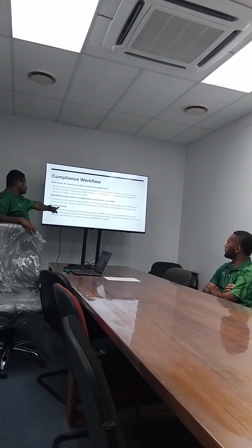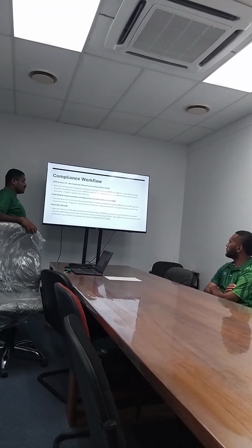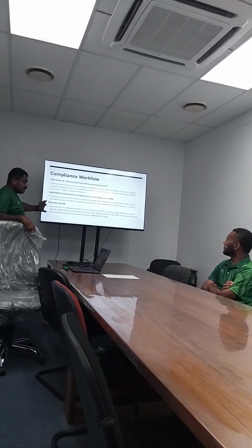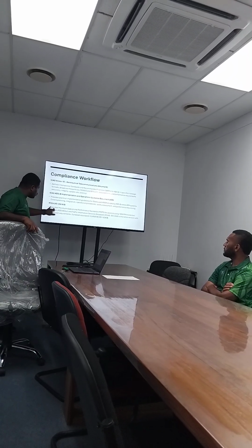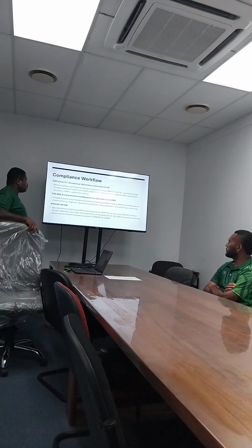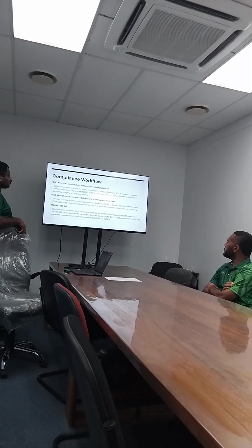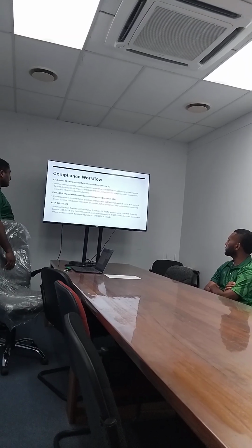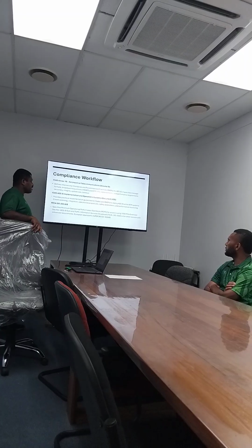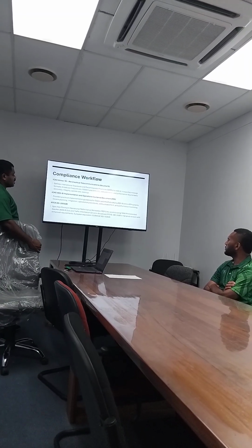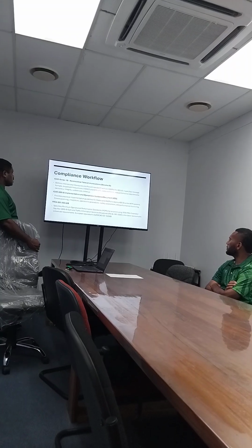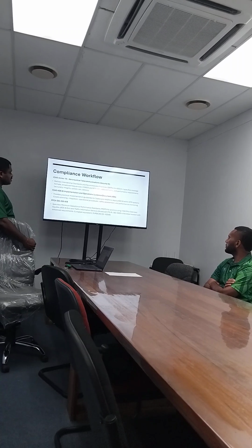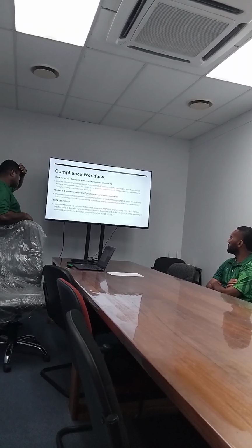The RTCA DO-260B requires the message format. This is to do with the airline. Every airline needs to be following this guideline or this document. It specifies minimum operational performance standards for avionics using 1090 MHz Extended Squitter ADSB and Traffic Information Services-Broadcast, or TIS-B. DO-260B is the latest revision with enhanced requirements and is equivalent to the EUROCAE ED-102B, that's the European standard.